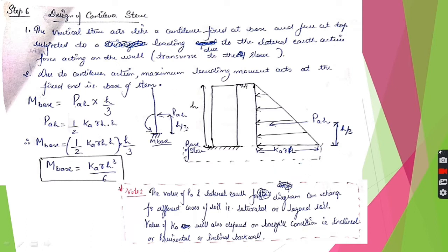The design is very simple. You just need to know few basics of design. So for design, as I always say, first of all you need to know the structural behavior of that part. So I have repeated it many times. The stem behaves like a cantilever with tension phase here, and the load acting is this. What is this load? This is actually the lateral earth force acting on the retaining wall.